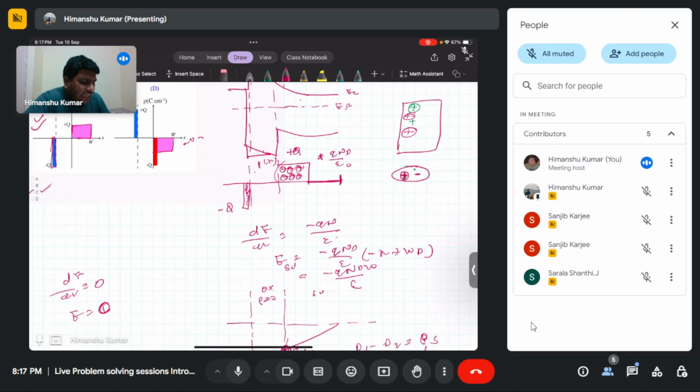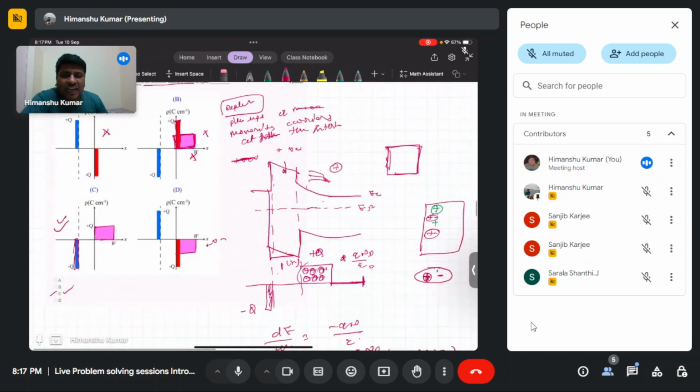In the practical case, depositing this oxide in practical devices has been a huge challenge. The phenomenon of field effect was discovered around 1920, and people knew that the MOSFET would work. The problem at that time was that people were not able to get that interface properly. It had huge charges because the material deposition and growth processes were not there. The oxide was very bad, so people were not able to test this phenomenon of the MOSFET experimentally.